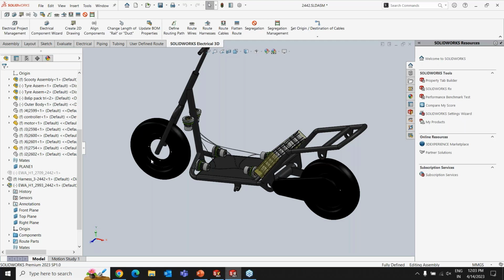Dinesh sir is asking if we should place the mating connectors in the model before starting the route. Yes, either as an electrical engineer you can place them, or you can have your mechanical engineers place them based on how they want it. After that, you can convert it into an electrical connector and then go for the routing.